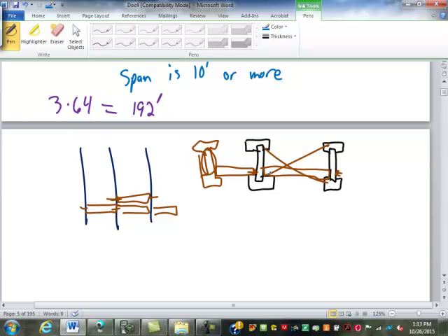The advantage to the X bracing is in how a floor joist fails. It's not because it usually sags so much it breaks. Where a floor joist usually buckles is it starts to sag, and as it's pushed down, it starts to twist off to the side a little bit. That's when it usually will crack and fail. It's very, very difficult to push straight down on a 2x10 or even a 2x12 and get it to bust. It starts to twist and then it'll bust.